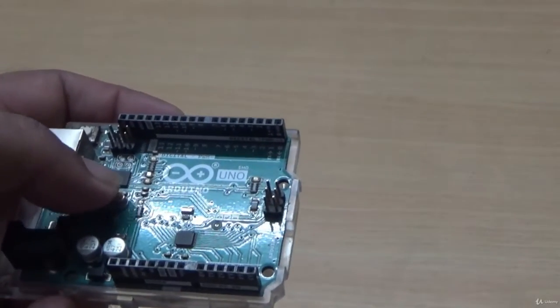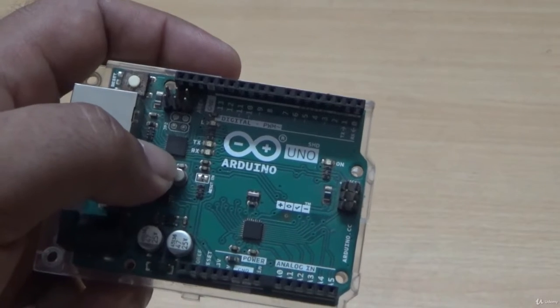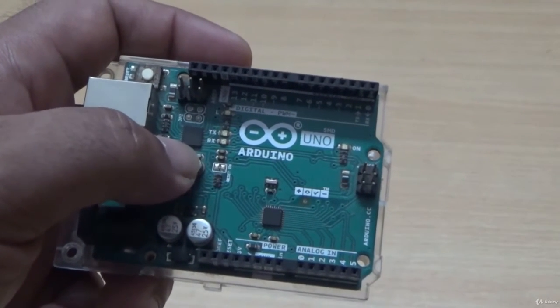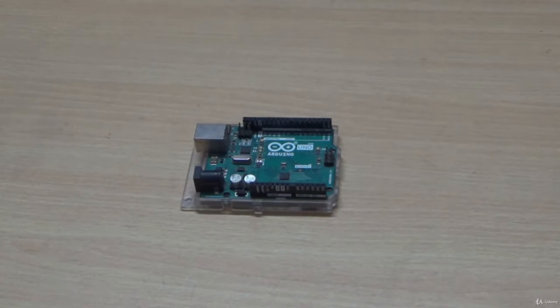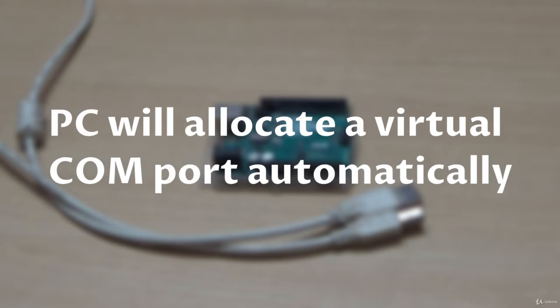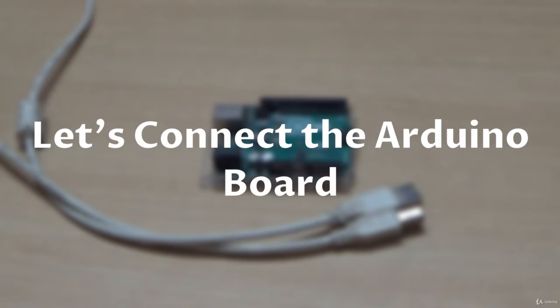Then this USB UART chip gets activated, and as you have already installed Arduino IDE on your computer, the driver for this USB UART bridge is already there with the Arduino IDE. So you will get a virtual COM port automatically. The PC will allocate a virtual COM port automatically to this Arduino board. That's how we connect Arduino.